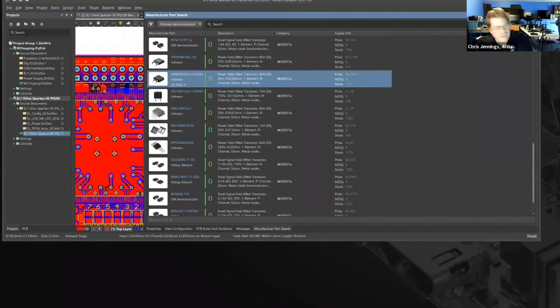And if you don't want them coming after you, you'll pick parts that have footprints, for example. Otherwise, you're going to have a delay. And the layout engineer said, hey, it's great. Got this part made of unobtainium. Let me go. It's going to take an extra week because I've got to go get and create a footprint for you. So do yourself a favor, only use parts that you have footprints for, unless you really hate your PCB layout guy.